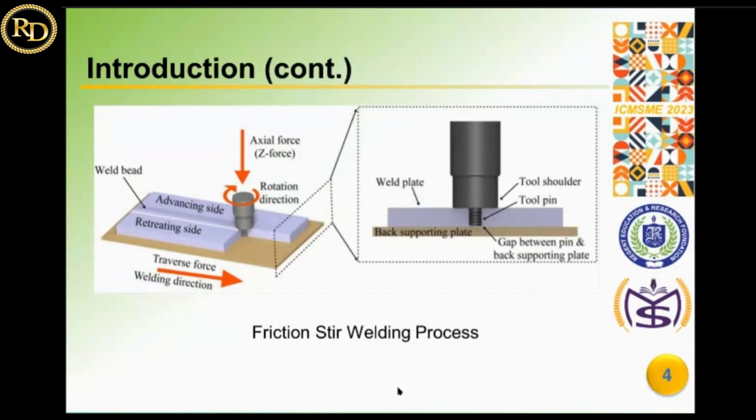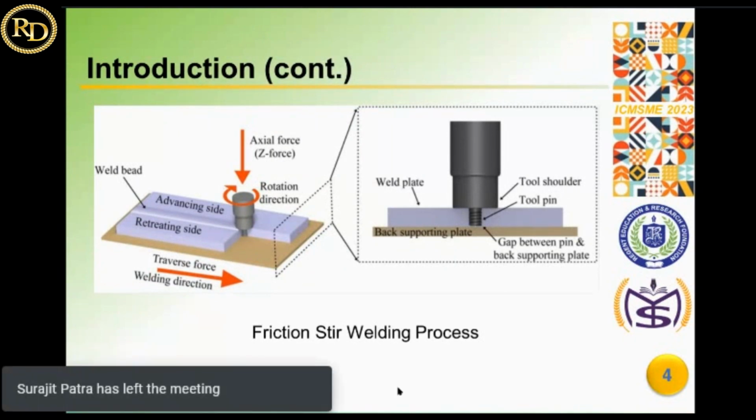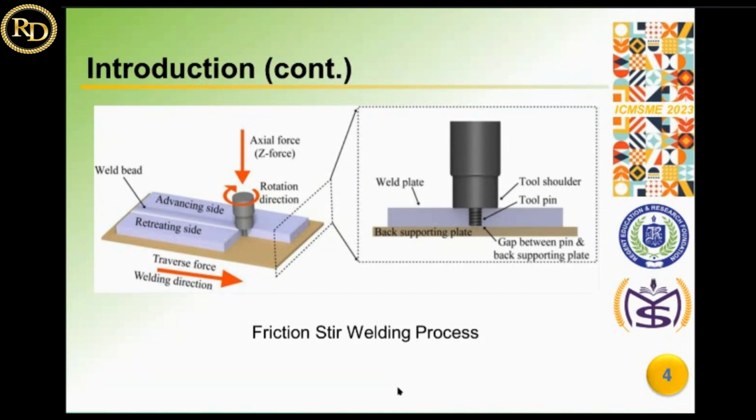Friction stir welding is based on the idea that when a particular amount of pressure is applied to the material of the workpiece, a non-consumable tool made of solid steel rotates to generate frictional heat, which causes plastic deformation. Without attaining its melting point, the rotating tool plasticizes the material as it moves along the joint line and physically combines the materials by stirring.